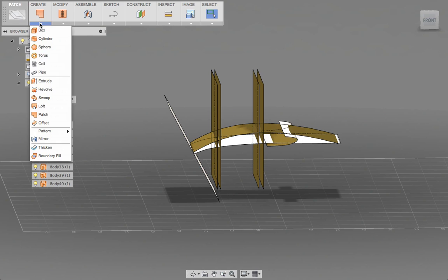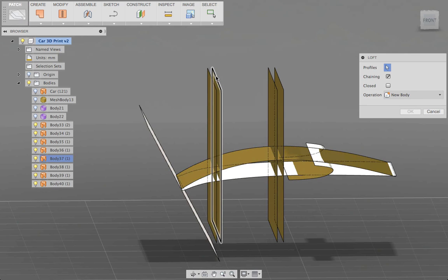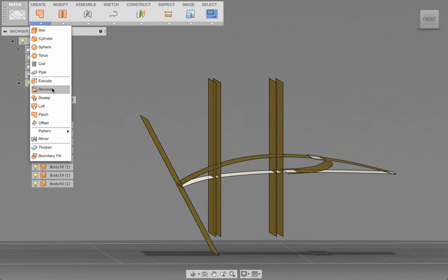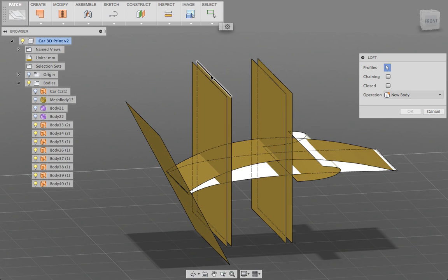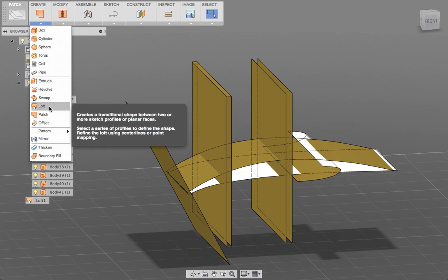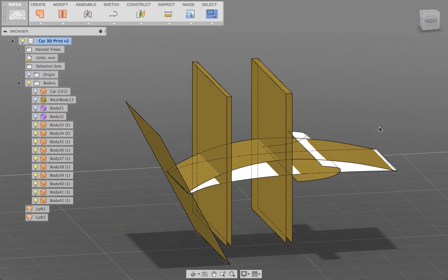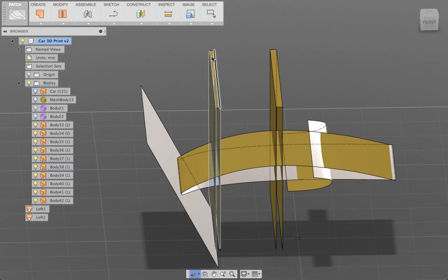I have the loft command, so maybe, no, hold on. Yeah, sorry, loft was correct. I just have to turn off chaining, so I can select this edge and this edge, and then do the loft command again, U and U. And the main reason is I can select now those objects, stitch them together,